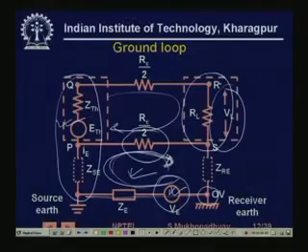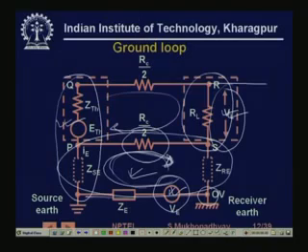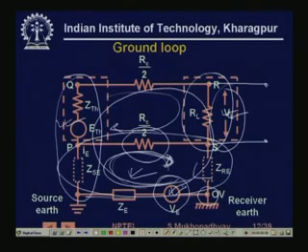So, you can see that when you make single ended measurements, because of these ground loops you are going to get errors. That is why for more accurate measurements we must make differential measurements, where we take both of these, and then some of these effects will go away, though some effect can still be there, because some current will flow through this path also.